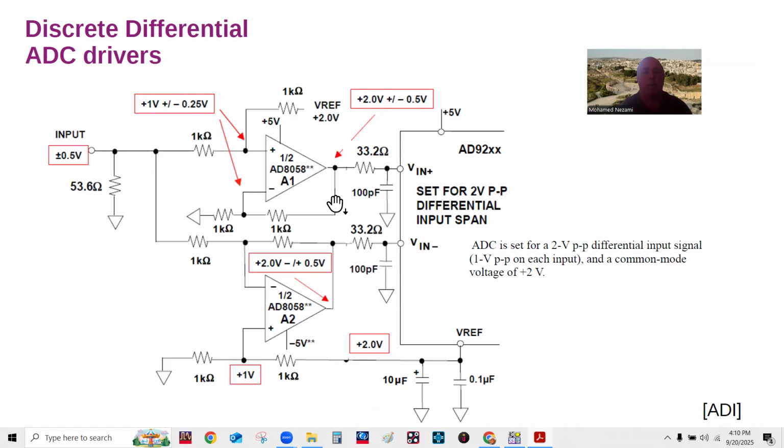Okay, and then the same thing in here, except since it's non-inverting and we have two equal resistors, that's basically the gain of 2 in here, and that gives you 2 volts. So we've got the signal in here, and we have a gain of 1 in here. Oh, I'm sorry again, hold on. The DC offset from these 2 points has to be 2 volts.